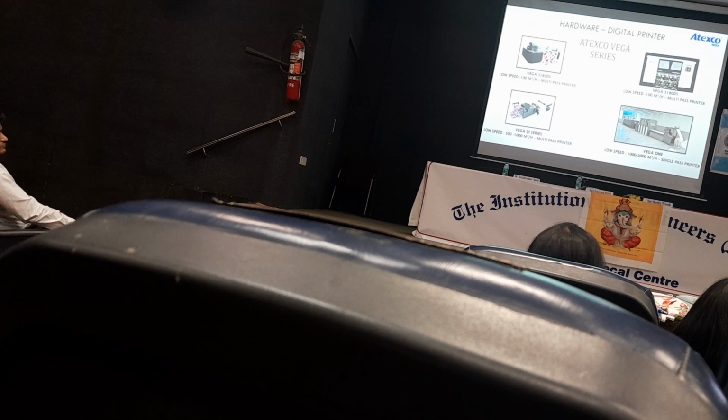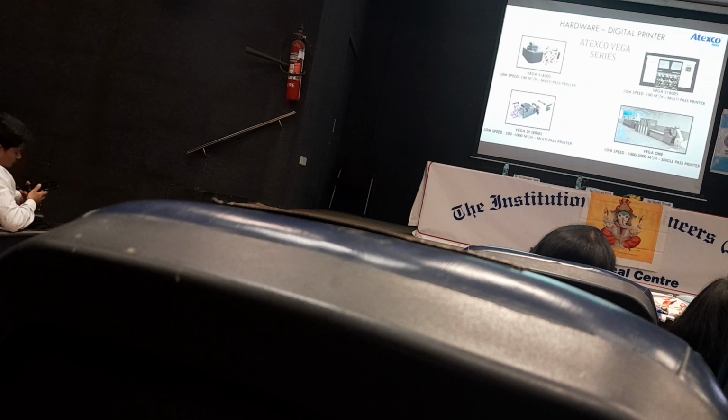And then there is single pass printing. Single pass printing is like rotary printing, and multi pass is like flatbed printing. Every time it steps, the blanket and scanner move like a scanner, right to left, and every time fire the inks from right to left. This is multi pass printing. In single pass printing, the blanket continuously moves, and the printers are steady and fire on the fabric.